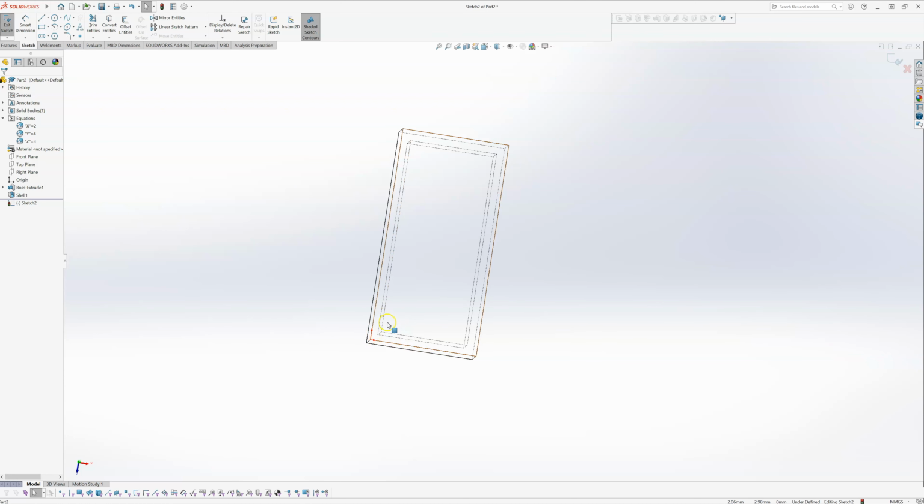The reason for that is that, let's say if I reduce my global variables here down to 1 by 1, there'll only be one stud left, and it'll be this one here in the corner. Okay, if I was to pick this corner up here, I might wind up with some issues there. So I'm going to pick the bottom left hand corner, the one closest to the origin, for that initial stud.